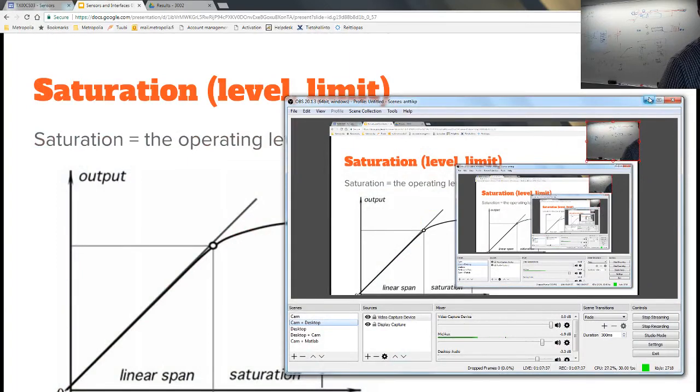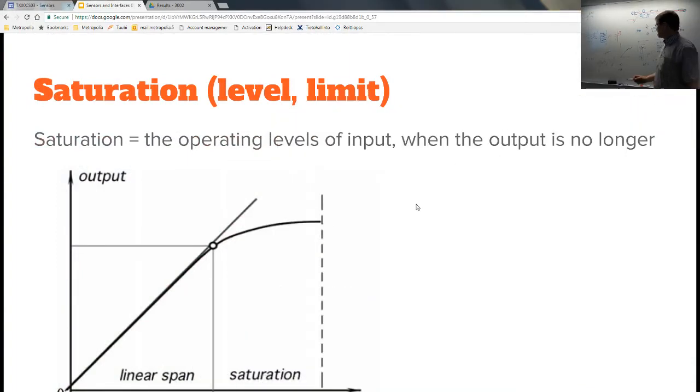Exactly like in this picture. So it starts saturating. Normally, that's where you stop measuring. But if you really have to have very wide dynamic range, more than 100 dB, so if you want to measure very, very small amount of light with the same experiment, using, let's see, 100 dB is 10 to the 5, 10 to 5 more light, and still have measurements, so not just guesses, not just nice pictures.